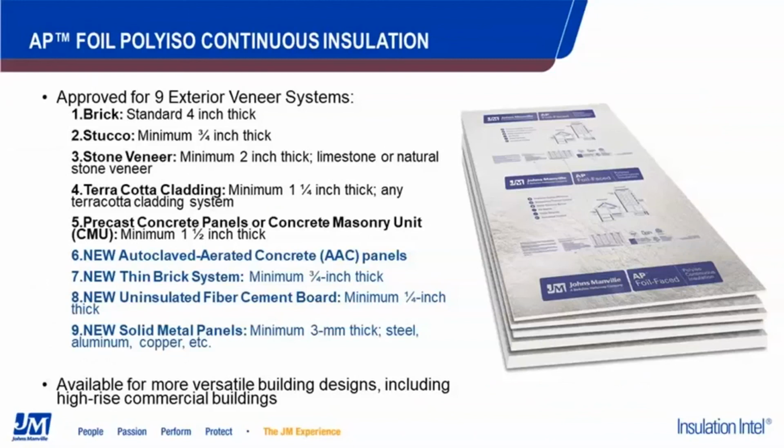One thing we did want to bring to your attention in relation to NFPA 285 is some new available cladding options with our workhorse, if you will, in the exterior wall assembly foam segment, our AP Foil continuous insulation, the polyiso product. You can see the claddings we had available in the past, and with some recent testing and approvals, and with all the information available to the public, we've been able to pick up some new claddings. They're autoclaved aerated concrete, thin brick, fiber cement board, fiber cement panels, as well as solid metal plate panels.